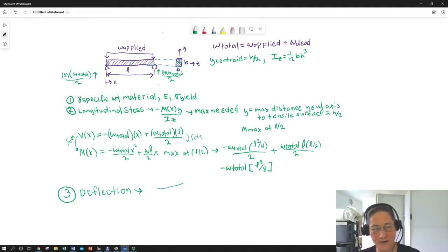So we're pretending that the end of the beam is kind of sticking up because it's deflected, and here's our original horizontal axis. So the beam's deflected because we stepped on it with a big load. So this angle. So the change of that deflection angle with respect to x is equal to the moment at whatever x we're at.